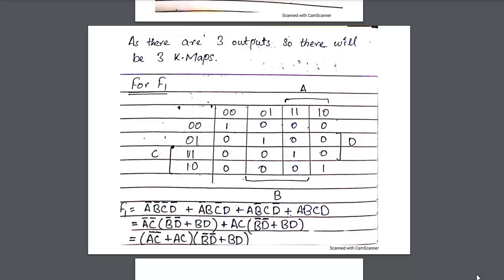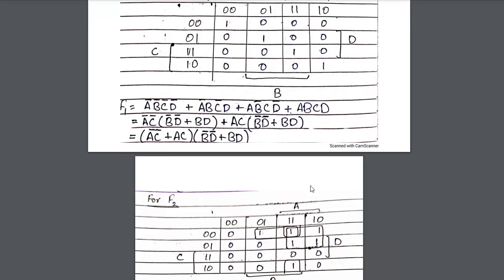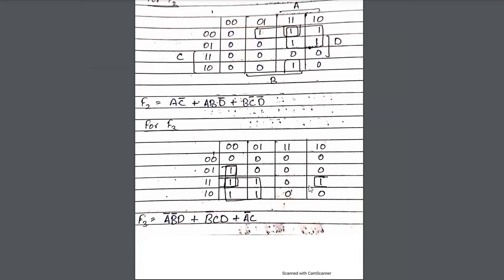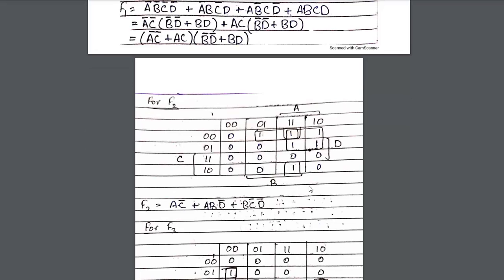After the truth table is designed, Karnaugh maps are used to derive proper and minimalistic inputs involving the least number of gates. 3 outputs mean that 3 K maps, one for each set of output, has to be designed, which also means that there will be 3 sets of gates.